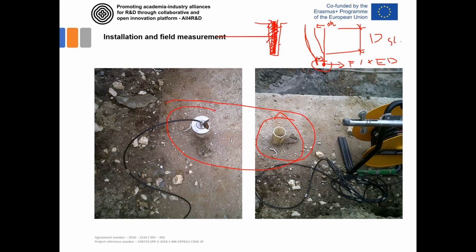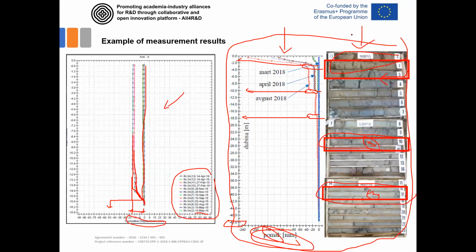That's why this point always has to reach some stable area. That's what happened here. Since the sliding depth here was expected to be 20, 30 meters, this borehole is so long. Boreholes went deeper and deeper just to be sure that we reach a stable area, so there is no displacement observed here, and then we recognize some displacement here.